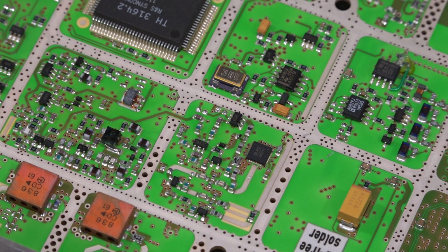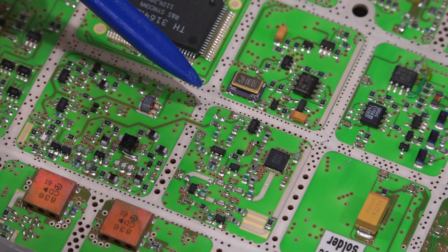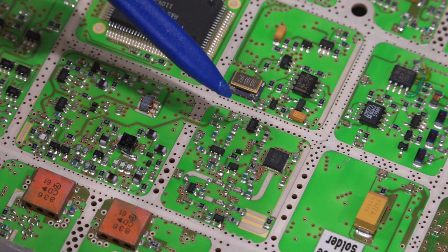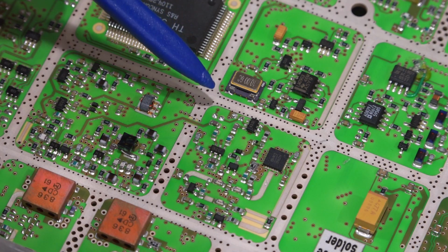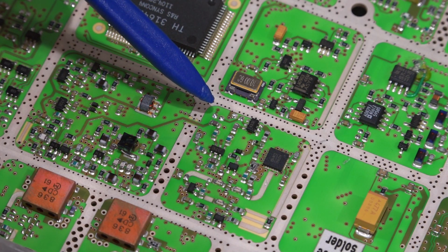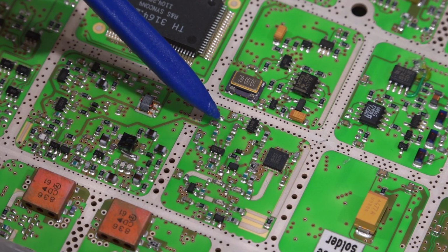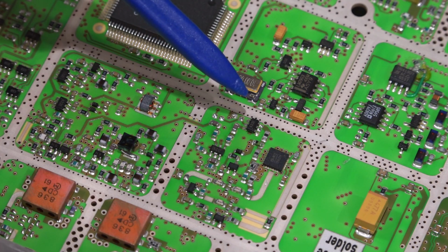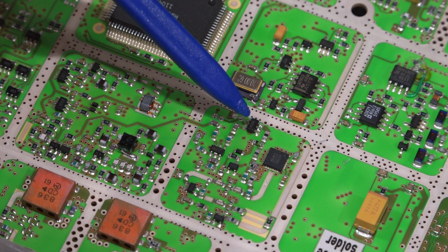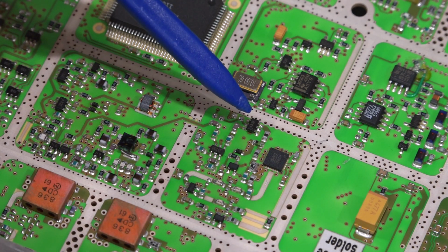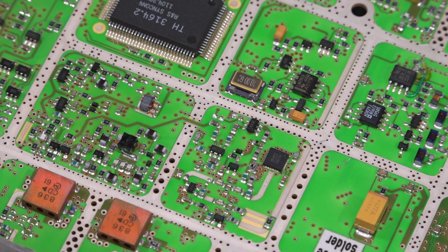So here we go. What I did is I removed the resistor, which was right over here, and I also removed this capacitor, and I'll explain why that is. I did that after making a few measurements here. So the goal is I'm going to put my ammeter across this resistor, essentially forcing the current that used to go through the 1 ohm resistor to go through the current measurement, and that allows us to power this on safely through that and figure out what the power consumption of it is. If the current flowing through it matches a datasheet for this part, then this part is probably not damaged to begin with. So let's do that experiment.